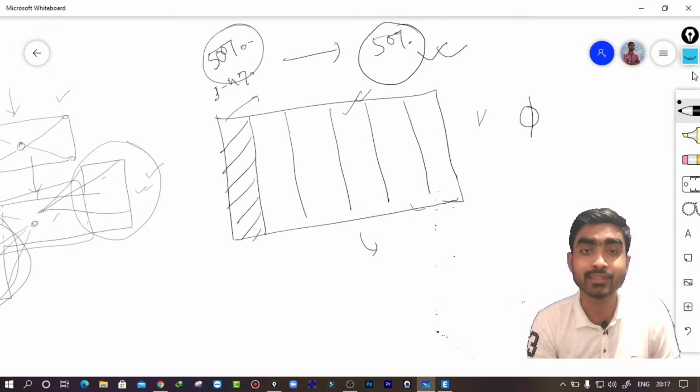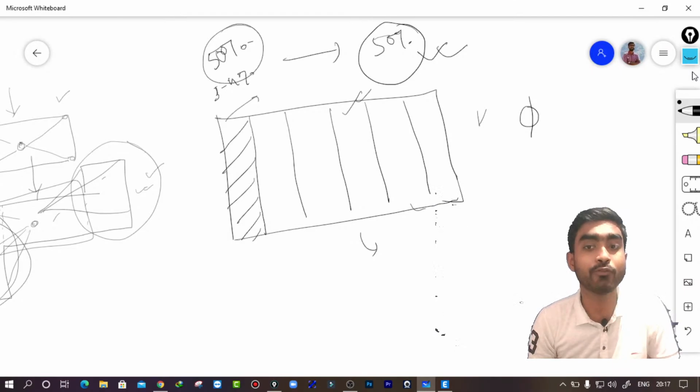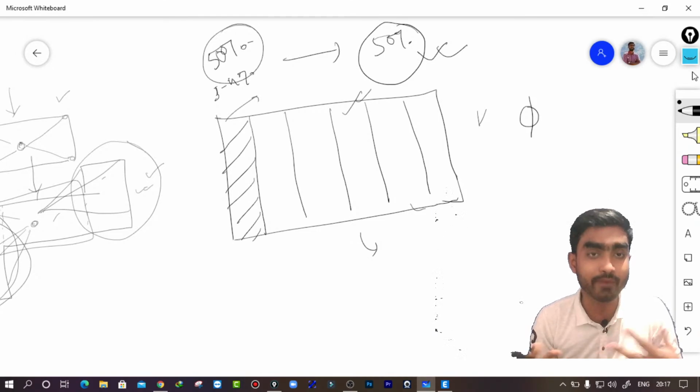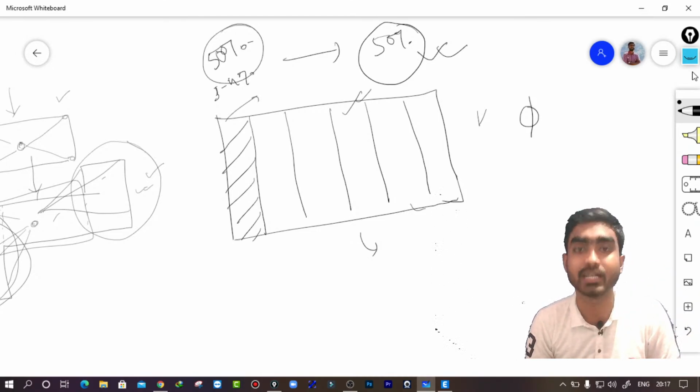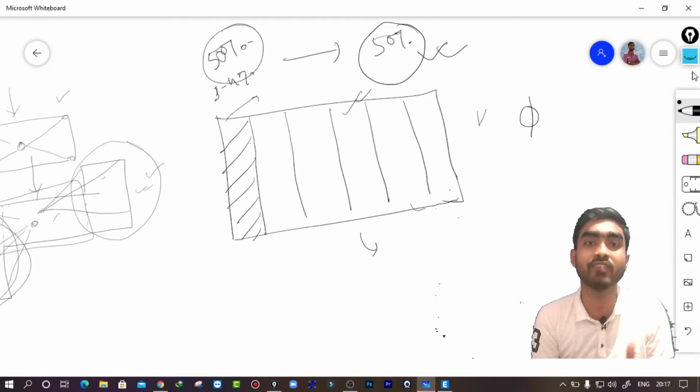So that's why the actual, basic behavior of the structure should be corrected before assigning the lateral loads. To understand the actual behavior, the basic vibration, the free vibration of the structure, we should go with 90% of the mass participation. That means we have examined most of the behavior of the structure.